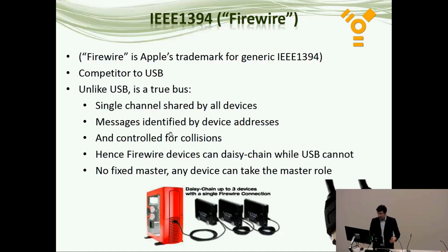There's a nice collision control protocol built in here. Again, unlike USB, there's no notion of a master and a slave here. So any device in a FireWire bus can take on the master role. There's a protocol where they negotiate who's going to be in control of the bus. And then when you take that role, it's your job to make sure that people aren't speaking at once and trying to write too much stuff on the bus at the same time.